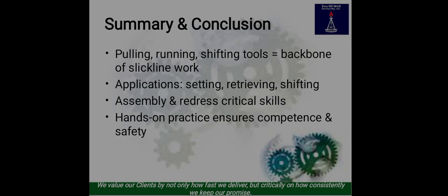So at this point, a B-type shifting tool was mistakenly used. Also, the tool had not been properly redressed before the job. Poor maintenance culture. So my emphasis here is that tool identification and maintenance must never be assumed by any operator. They must be verified. If possible, have a second eye to verify it, not just you alone.